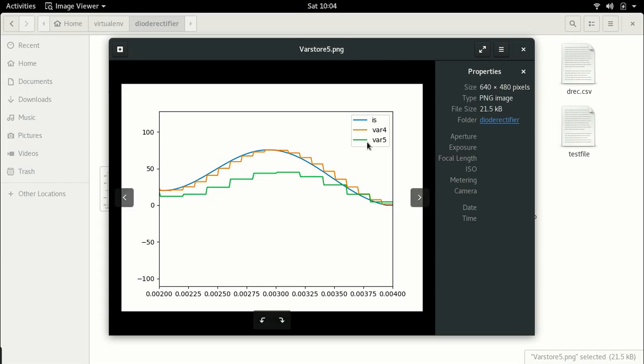Why? Because the second control file is sampled at 200 microseconds. The first control file is sampled at 100 microseconds. And this first sampled current is fed to the second control file where it is sampled at a different rate. This is the flexibility of the circuit simulator. You can have different sampling instants, you can have different control variables, you can do whatever you want. You can run a PI control on the first one, another PI control on the second one, so you can have multi-rate control. You can have an inner fast control and an outer slower control.